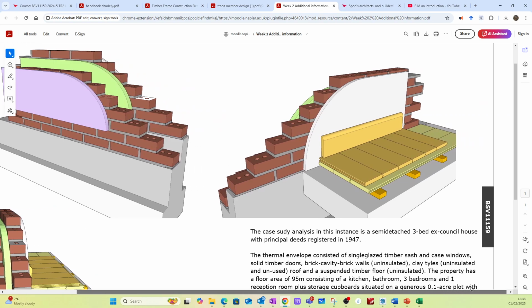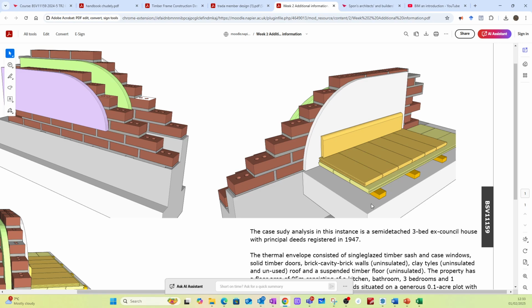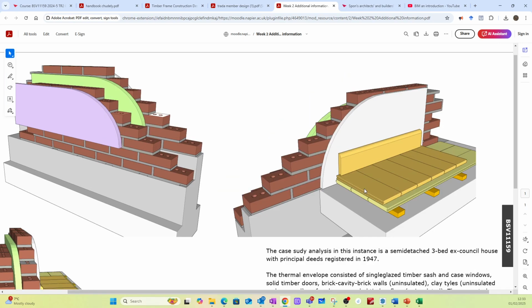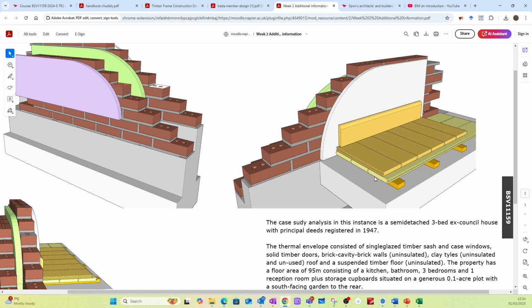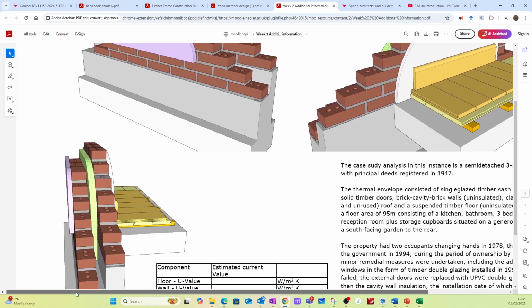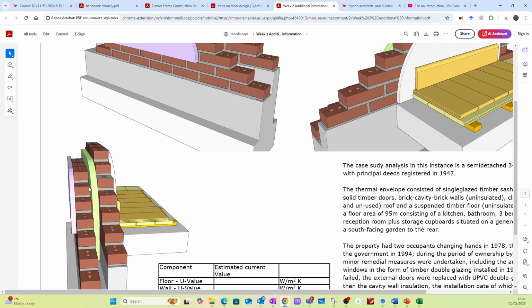And then you've got a concrete floor. On this particular example, it's actually a screed of concrete on top of the rock. And then you've got a 25mm by 50mm batten with softwood, probably pitch pine to be honest, softwood floorboards. And then the current resident of the house just put hardwood flooring on top of that, actually 22mm beech flooring. So that's that. The house would have started off originally without any cavity insulation, so it would have been render, brick, 50mm cavity, brick, and then plaster.